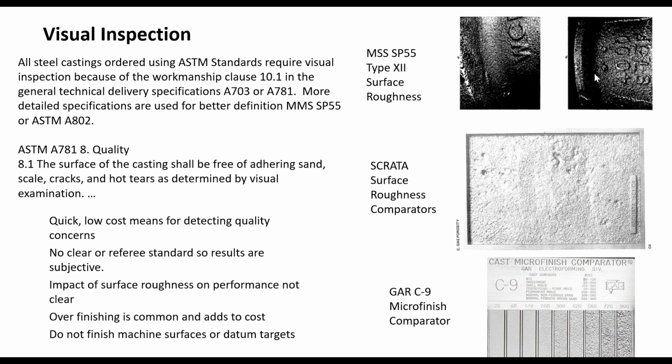This one's unacceptable. So you can see that if we're looking at the same casting and I am the foundry, I think that the casting looks like this. You as the customer think the casting looks like this. And so we really have a difficult time agreeing on what that means. In fact, most of the non-destructive standards are really a handshake between the foundry that's producing and the customer that's buying it, because none of these standards are quantitative where you can get a measurement as a refereed standard.